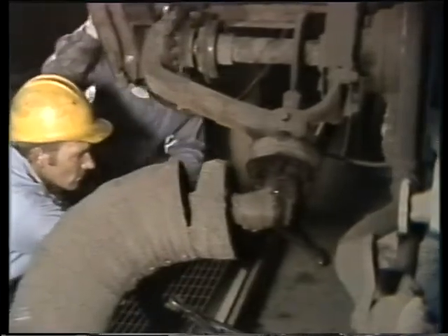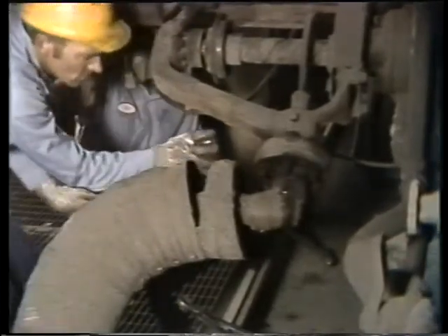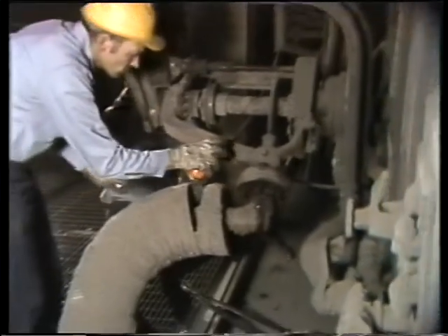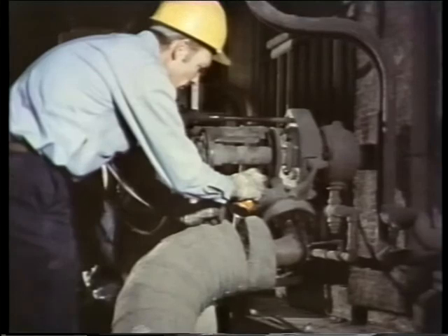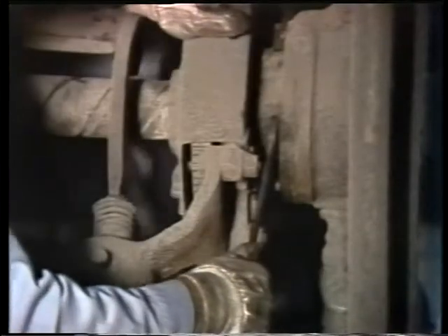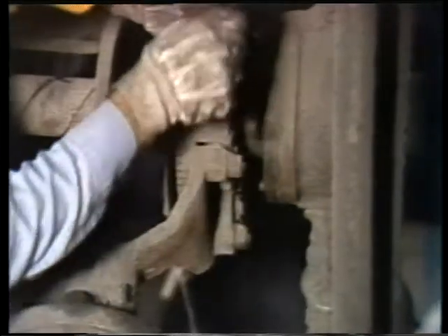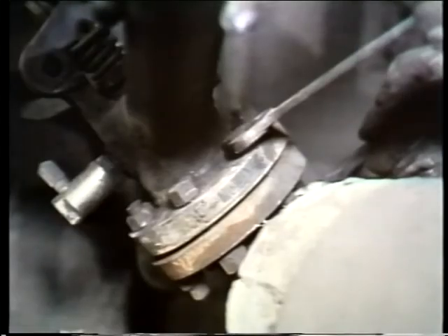It's a good idea to shoot some penetrating lubricant on the nuts and studs that have to be loosened. They could be awfully hard to break loose without it. Using an appropriate wrench, each of the nuts that holds the soot blower to the boiler wall mounting can be loosened. The same goes for the nuts that hold the flange connection to the piping for the blowing medium.